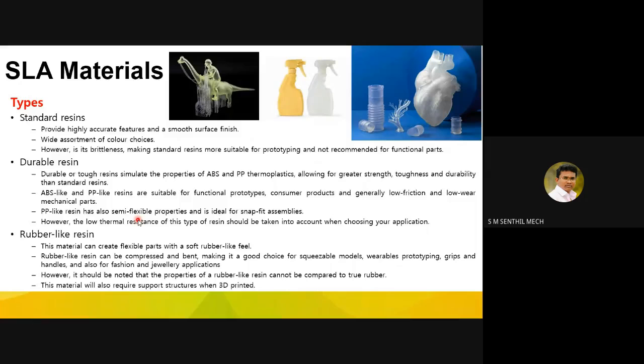Okay, so if you are pressing it, it will be getting fixed into the earpod. So that is a snap fit. Such kinds of applications can be done using durable resins, but they have low thermal resistance, so they can't be used for high temperature applications. These are the durable resins.